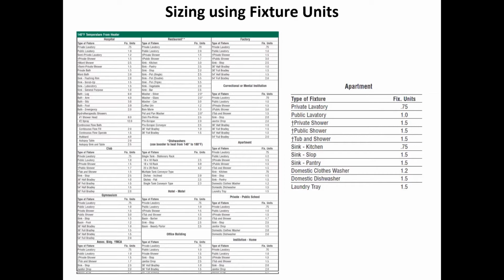That's of hot water, right? So that would be a mix. So that 1.5 is like 2.2 gallons per minute of shower flow rate, which is a pretty standard shower now. And then of course, Energy Star is a 1.5 gallon per minute shower head, and then 65% of the 1.5 gallons would be hot. So really they are maybe a little bit oversized for Energy Star type applications.